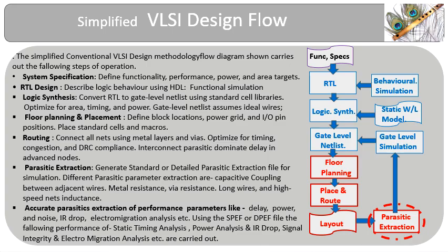The VLSI design process defines the system specifications, performance parameters and goals of power, area, etc. The RTL design using HDL implements the logic and simulation verifies its functionality. Logic synthesis converts it to a gate-level netlist and ports the design to the appended standard cell library. Floor planning sets block locations, power grids, and I/O pin positions. Placement arranges standard cells and macros within the layout. Routing connects all nets, vias, metal layers and ensures timing and DRC compliance.